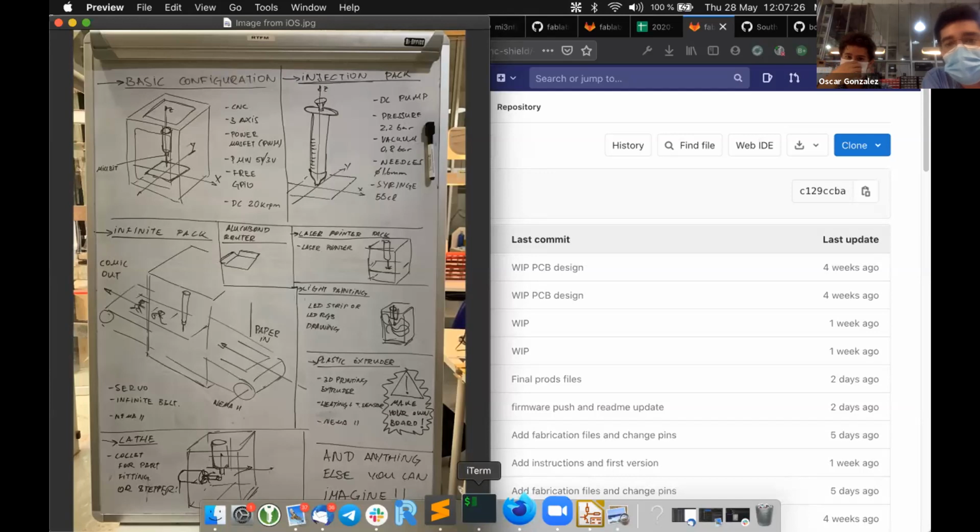If you are moving in the diagonal, you need to move at the same speed in X and Y. But if you are moving slightly tilted, making a 20 degrees line, the speed in one direction is different than the speed in the other direction. And sometimes they need to accelerate at different rates, so that they actually make a line at 20 degrees.